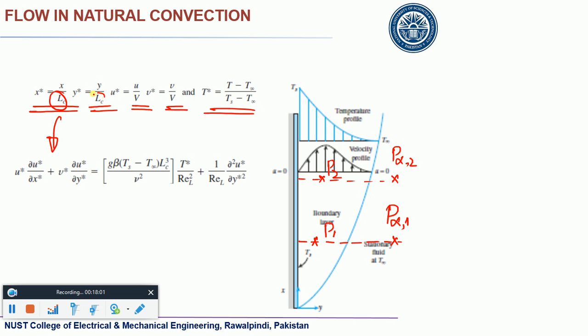You see, this is the characteristic length. Remember that this characteristic length is not about the flat plate length only. It would vary, and it would depend on the geometry. Even if you give a small inclination to the plate, this characteristic length would change. So it is very important to see that the characteristic length is even determined by experiments.